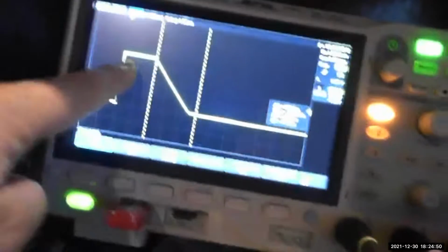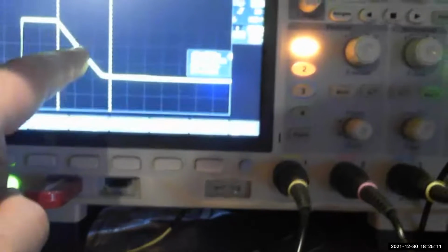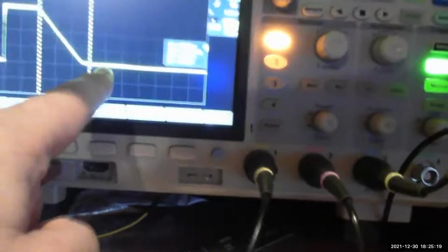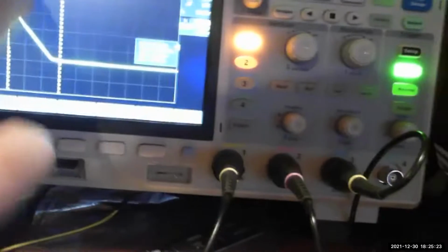And this time here is the discharge of the capacitor. I put out a one on the port and force the capacitor to go up. Then the pin becomes an input, and I use it as an analog input, wait for 600 microseconds and measure the value at this point. And I am subtracting 1024 minus the sampling value to make white the highest number and black the lowest number, because the ramp is inverted.